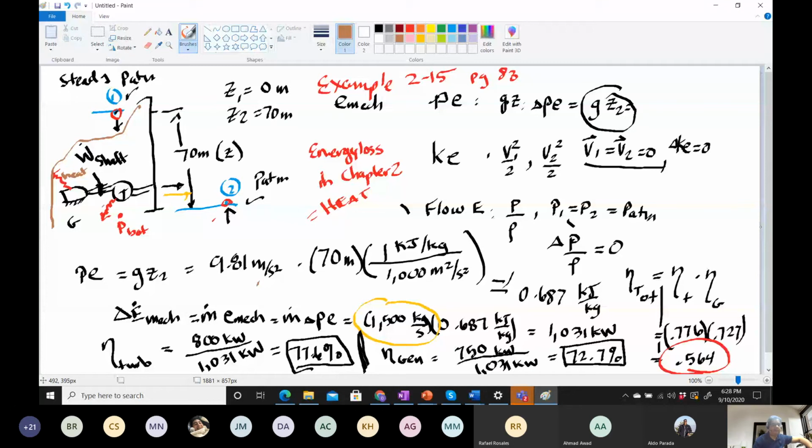So the mechanical here is basically height, or what we call head, or pressure, and it's converting it to shaft work. So you're right. Generators tend to be very efficient, upwards of about 90%, because they're converting mechanical to electrical, and the windings and everything like that are done to the point where you can easily get 90-something percent. Turbines are trying to capture some of the pressure of the water, and so they're a lot less efficient. Okay, yeah. Great. Thank you. Good point.